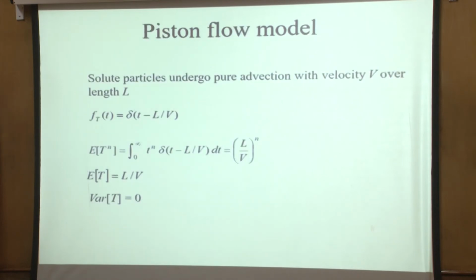Okay. Let's say, so the advection dispersion model was one model. I have another model, the simplest model that I can think of to start with, piston flow. That means no dispersion. So it assumes that all particles are traveling with the same velocity. It's a sharp front model. Each of them has a velocity of v. So if I had introduced those 1,000 particles, all 1,000 particles would be traveling with an effective velocity of v. They would all come out of the soil column at one particular time. At all the other time intervals, you'd be getting 0 particles.